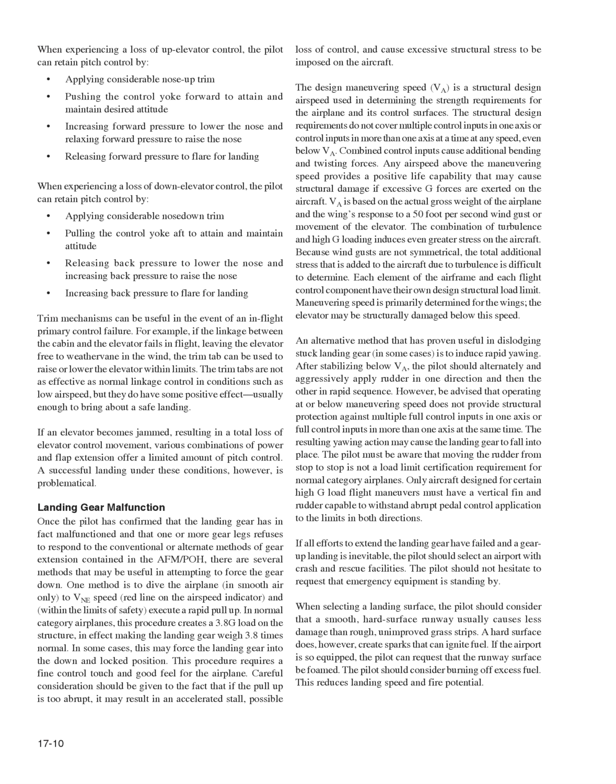When selecting a landing surface, the pilot should consider that a smooth, hard surface runway usually causes less damage than rough, unimproved grass strips. A hard surface does, however, create sparks that can ignite fuel. If the airport is so equipped, the pilot can request that the runway surface be foamed. The pilot should consider burning off excess fuel. This reduces landing speed and fire potential.